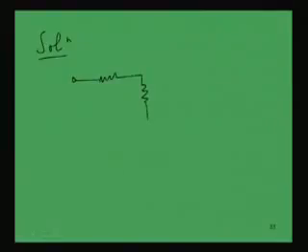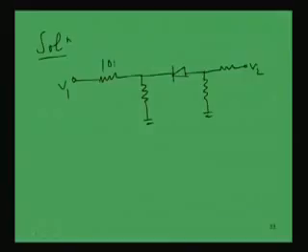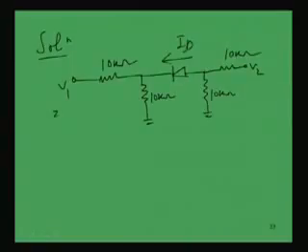Again we draw the diode and the resistances, like this is ground, this is ground, this is B2, this is B1. The resistances are all 10K, 10 kilo ohms, and we have to find out this diode. This B1 is equal to 10 volt, B2 is equal to 15 volt. Now, you see what voltage is being applied across this diode. VD will be, VD means the voltage across this diode.